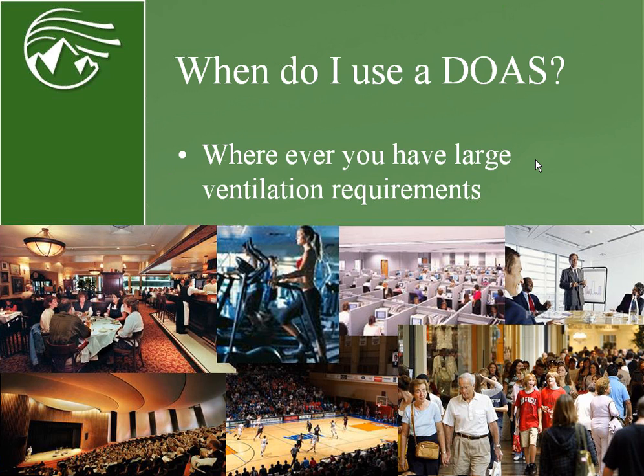So when exactly would you use a dedicated outside air system? Basically, we're looking at using these systems whenever you have a large enough amount of ventilation where you're concerned with having to heat or cool it. When you have so much ventilation air coming in that at a negative 10-degree day, you have to worry about tempering that air to a comfortable level to bring into your space.